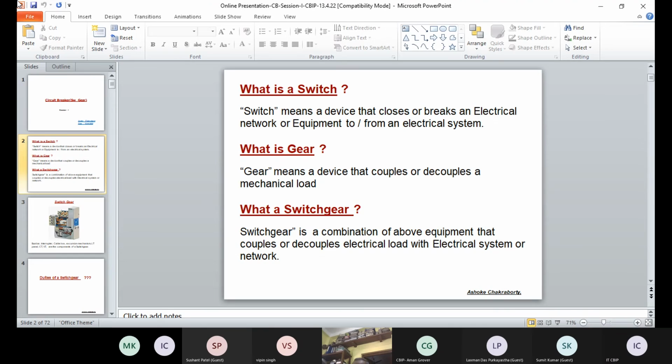Yes, sir. Before switching on a geyser, an AC, a refrigerator, a lamp or a fan, there was no energy inside it. Now, as you switch on, it consumes current and delivers work: the fan is working, the light is glowing, the refrigerator is cooling. In the process, the inherent inductance and capacitance connected with the load also store certain amount of energy. They are just like springs, storing energy. Whenever you switch it off again, as per the conservation of energy, it should go back to the zero energy condition.